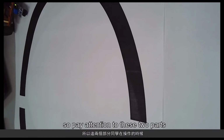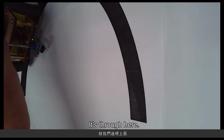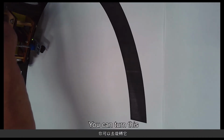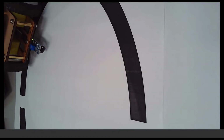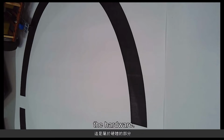So pay attention to these two parts. When operating this, remember to calibrate. How is calibration performed? It's through here. Take a Phillips screwdriver. To adjust the variable resistor on top, you can turn this to adjust it until its motion is normal. This is regarding the hardware.